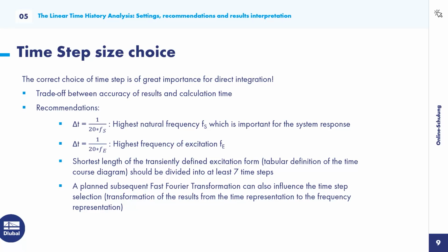And it's a trade-off between the accuracy of the results as well as the calculation time. I mean, you have to think about each time step being comparable to a normal static analysis, well, a little bit more complex since the dynamic equation is just a bit more complex. And for each time step, you have one of those analyses after each other, because you can't do it in parallel, but you have to do them after each other. And that's something where the calculation time, unfortunately, can explode.